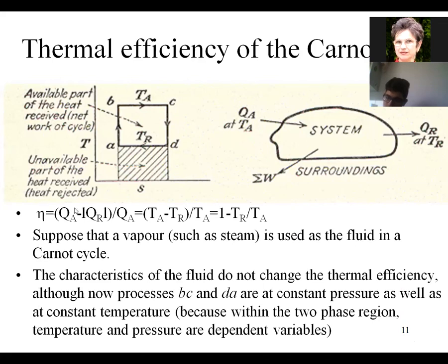So here is again the efficiency, given by 1 minus the ratio between the hot and cold reservoir. The Carnot cycle in a TS diagram is A, B, C, D, as you see it. A, B, a vertical, is an adiabatic warming up process, heating process. BC horizontal is an isothermal expansion. CD is a compression, but adiabatic compression. And DA is an isothermal compression.